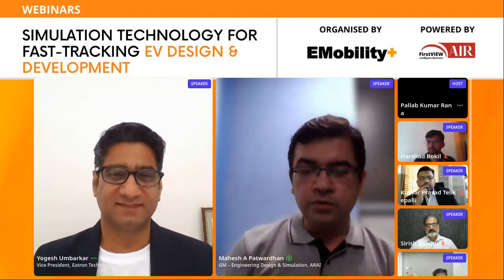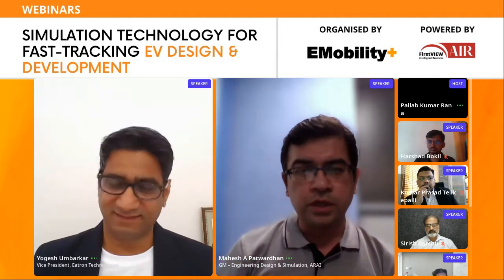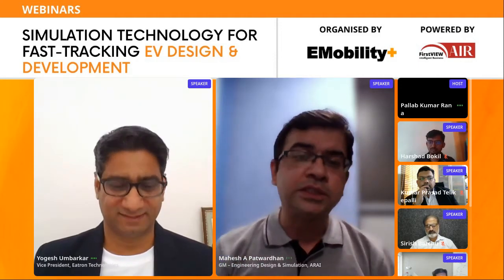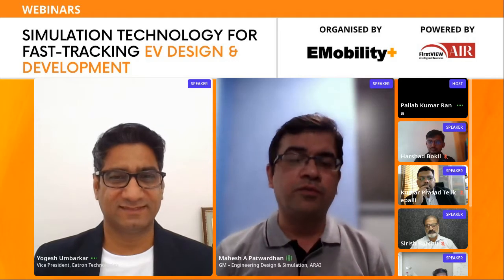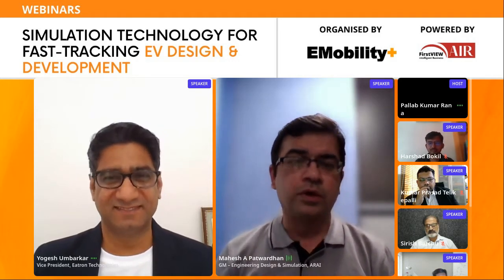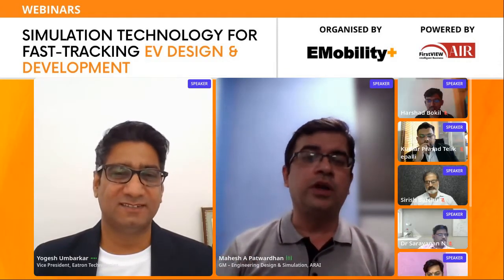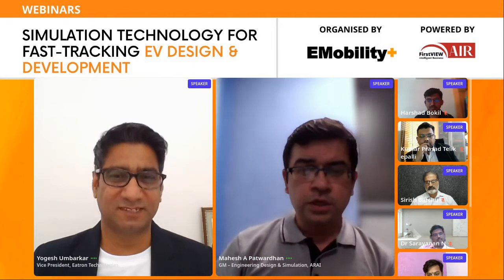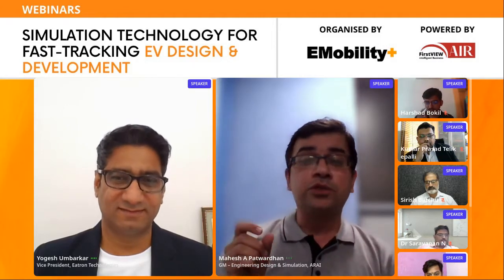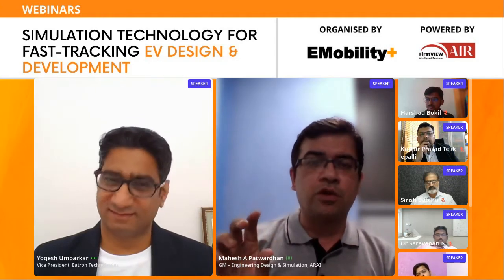But for EVs now, more than OEMs, more startups are coming in, and they may not necessarily be in a commanding position where they can demand a lot of input data from different battery cell manufacturers or battery component manufacturers. So the absence of that data poses a challenge in accurate prediction of EMI EMC.